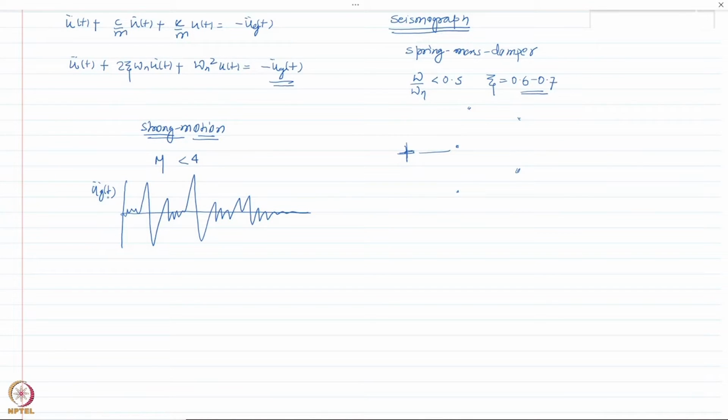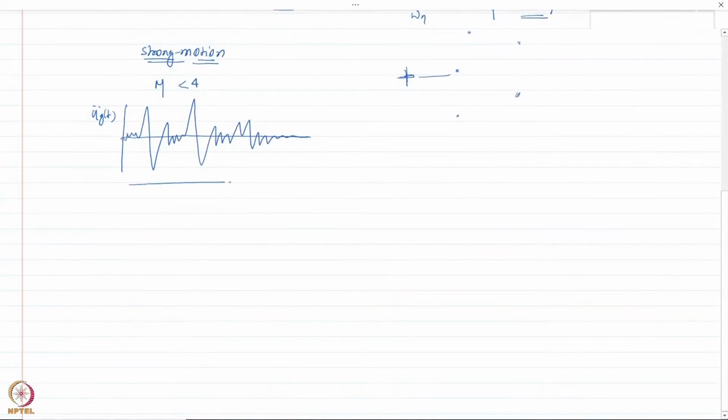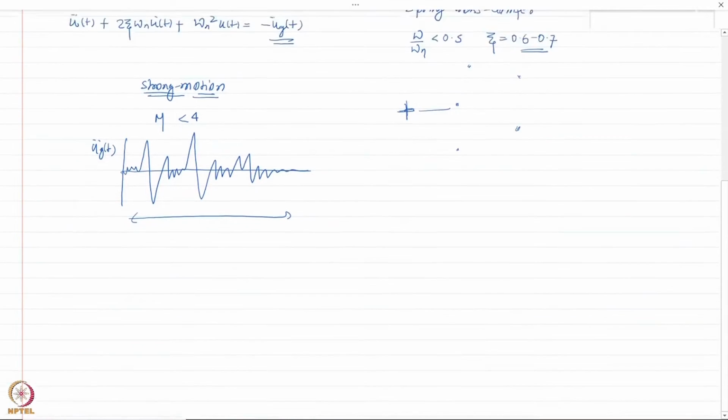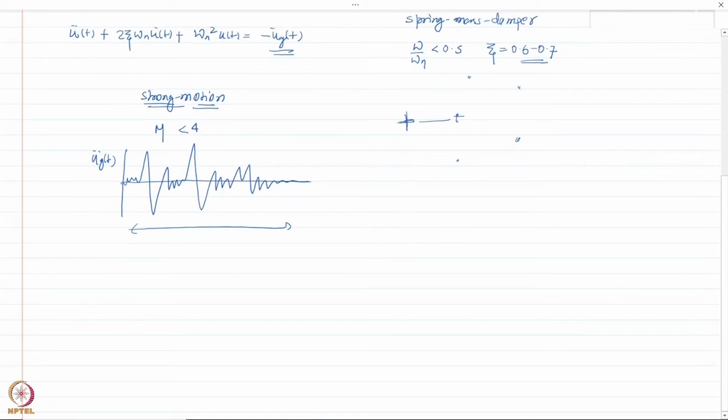So for strong motion duration, there are different ways to characterize it. There is Arias intensity, there is a threshold, or a duration with respect to maximum PGA, or certain kinds of things. But basically, just remember that these do not continuously measure, but measure above a certain threshold. And each of these accelerographs, which are located at different locations, can measure in one direction, two directions, or three directions, depending upon what kind of accelerograph they are. Two horizontal directions and one vertical direction.